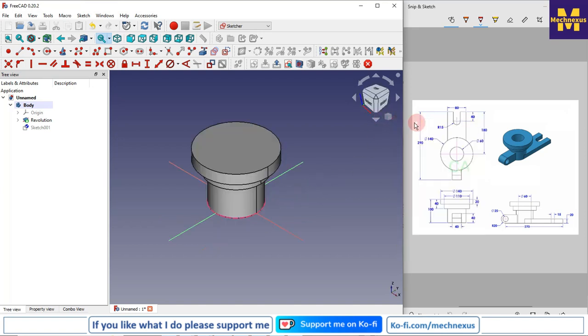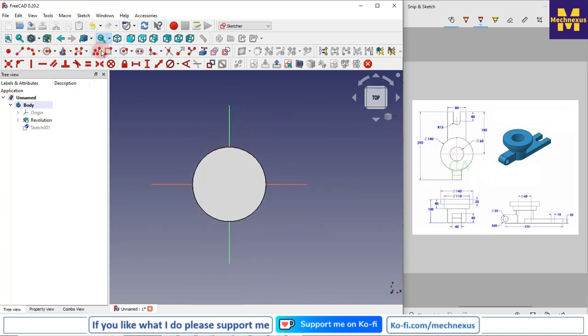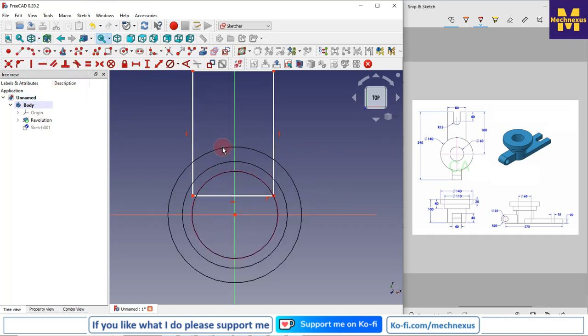Now I will switch to the isometric and click on the top view, and I will draw a rectangle, and I will switch to the wireframe view. Now I will make it coincident, and I will delete it. I will select this and give it horizontal. I will select this and give it horizontal.